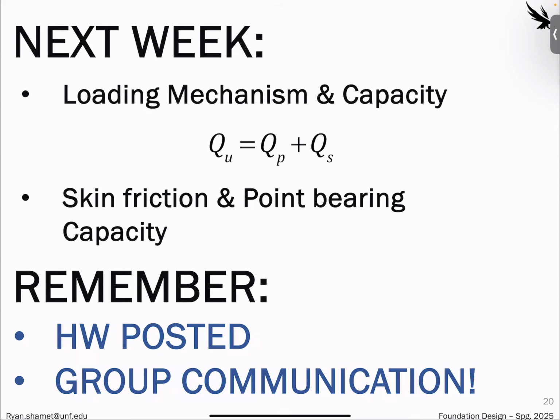For shallow foundations, you look at the capacity of the foundation in terms of a stress, because it's a force divided by an area. But with piles, we look at it in terms of a singular force, because it's a point that's being distributed. So what we see is that this ultimate capacity is a combination of two things, the point bearing and also the skin friction. But the tricky thing about this, and I'm just teeing it up for right now, is that one of them is going to occur before the other.